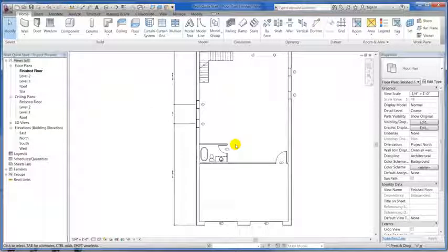That's because when you put it on a sheet, it's set up so that all your text, no matter what scale you're at, will be the same height. So if I was to print this on a 3/4 inch per foot scale, the text would have to be that tiny. That way when you plotted it on a sheet, it would be at the correct height, usually about 3/32 of an inch tall. If I plot a 1/4 inch scale next to a 1/2 inch scale, the text will be the same height. And that's architecturally correct. So Revit takes care of that for you. So there's your scale button.